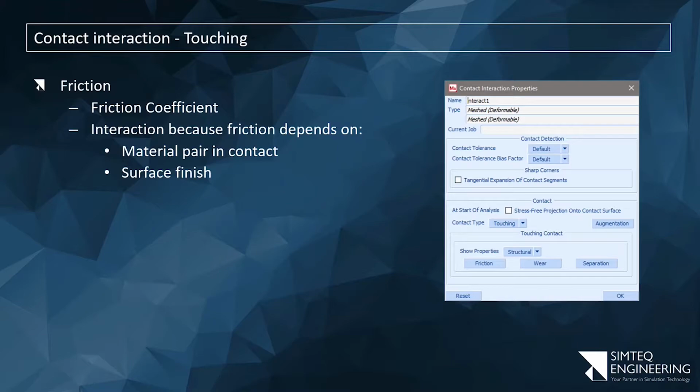So if I look at the first one, if I have Teflon on steel, the friction coefficient is around 0.01, but Teflon on Teflon is also about the same, 0.01. But if I look at steel on steel, that may be 0.1 or 0.3 or whatever, depending on the surface finish. So there's no way to specify on the contact body that would make sense.